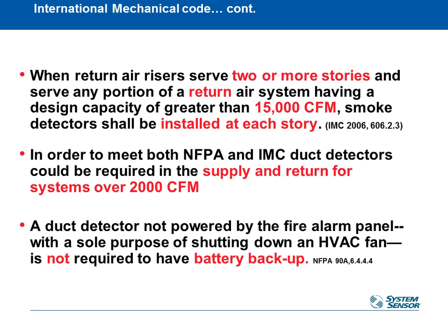The idea there being that if the HVAC fan loses power, it's already going to be off, so it doesn't matter. If the duct detector is powered off the fire alarm system or a more robust control system, then you would have to put it on the UPS because now the duct detector has a different power source than the supply fan.